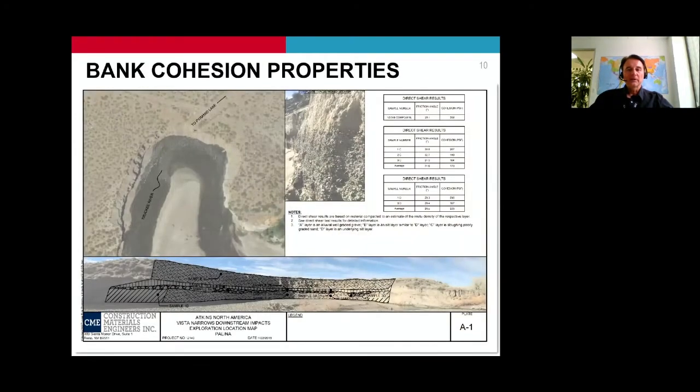At 5 critical locations with severe bank cuts and meander migration, bank samples were collected for direct shear tests to identify geotechnical stability parameters, soil cohesion, and internal friction angle. And these parameters were used in our fluvial geotechnical stability analysis and lateral bank retreat evaluation based on a model of wedge-type bank failure by Osman and Thorne.